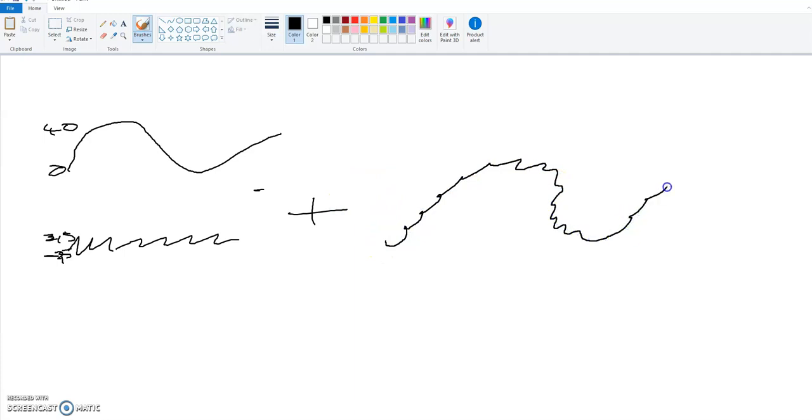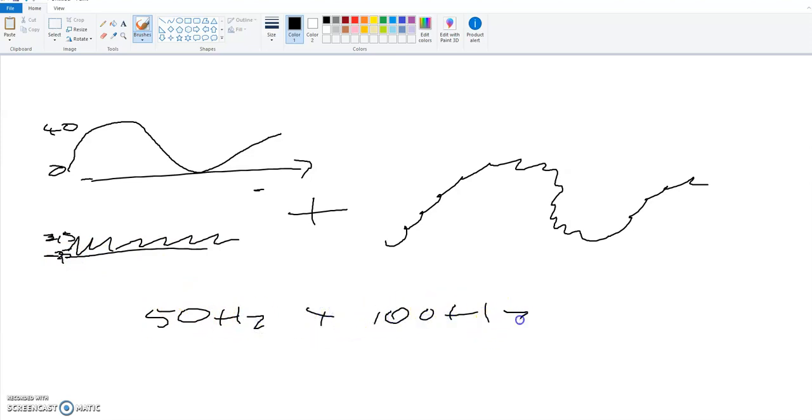We're going to see it now on the software. We still have to write a program to show you the waveform, but for now, this is what's happening. It's slowly going up, and every 2 seconds it's going to do a full cycle. Our highest frequency is 50 Hertz, and the Nyquist rate says double our highest frequency, which is 100 Hertz. So we have to measure at least 100 Hertz.